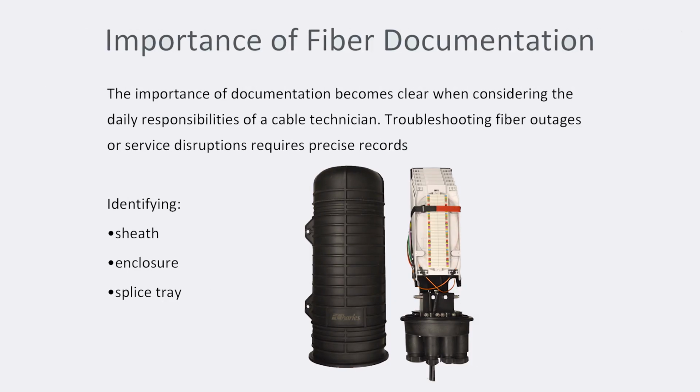The importance of documentation becomes clear when considering the daily responsibilities of a cable technician. Troubleshooting fiber outages or service disruption requires precise records. Without them, identifying the correct sheath, enclosure, or splice tray can waste valuable time, delay restoration, and extend customer outages.